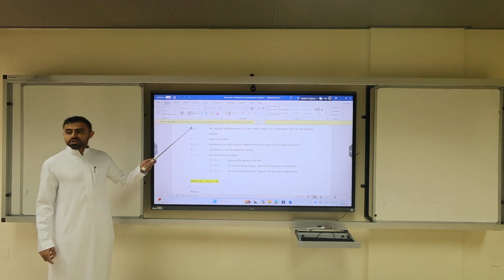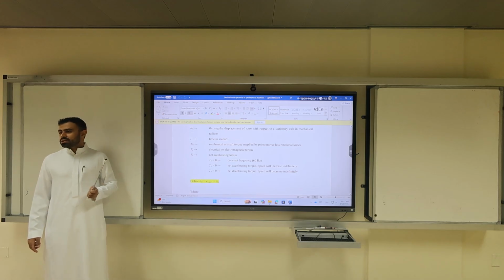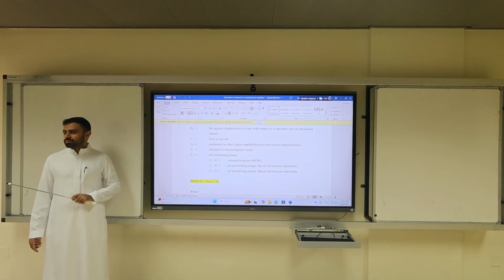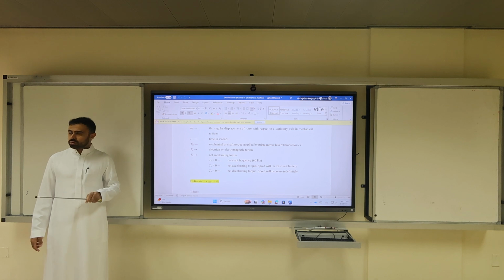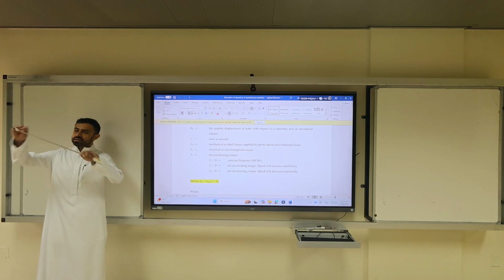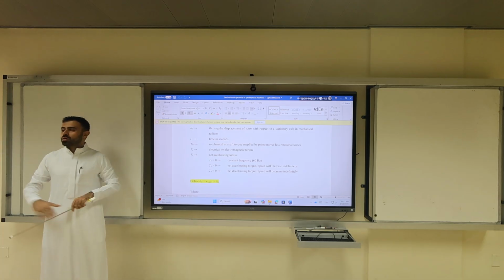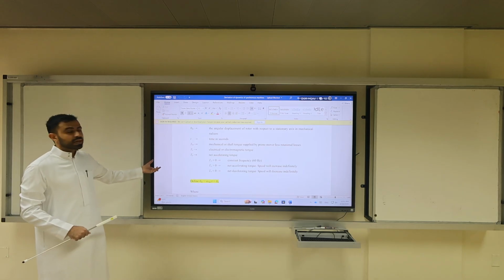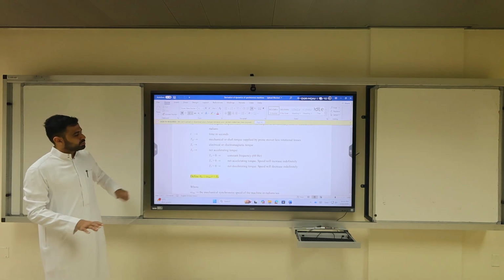And what's the relationship between mechanical degrees and electrical degrees? Theta E would be equal to P over 2 theta M. Okay? Or theta M equal to 2 over P theta E. If you have 4 poles, your electrical angle is half of the mechanical angle. It's half of the diameter of the circle, because half of the poles would cover what's equivalent to 360 degrees mechanical. It's not important now.